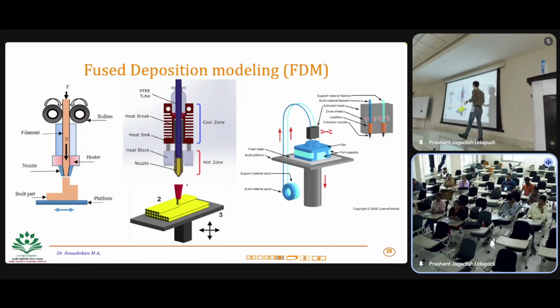And then, for example, for typical PLA or ABS material, anywhere from 180 to 230 degrees Celsius is the typical temperature at which the filament starts melting, right? Once you achieve that, since you are continuously pushing the material, and it is now in liquid form, as soon as you push the material, the liquid material will try to escape.